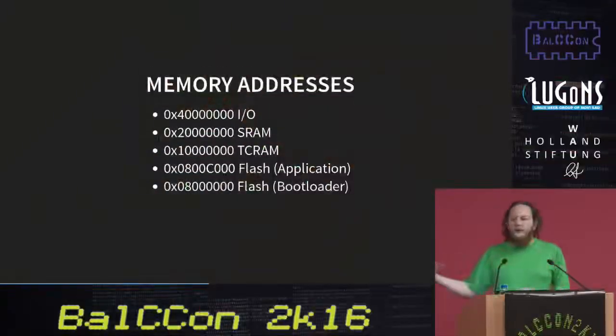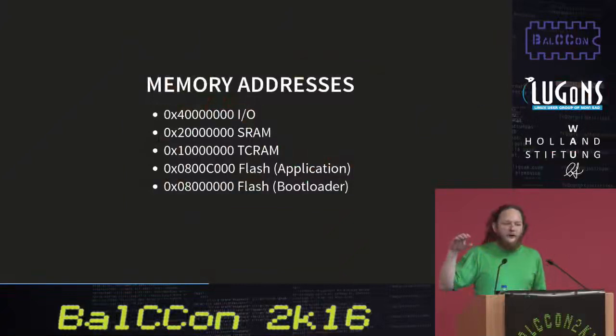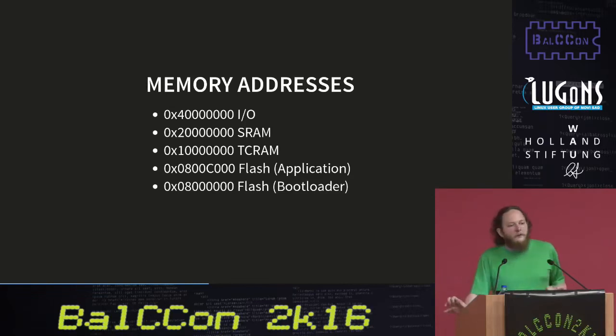The first thing you need to know is where things are in memory. Unlike Unix or Windows, where you have a varying memory layout per process with address-space layout randomization moving things around, on an embedded system, everything is stuck at a fixed physical address. And there is no such thing as virtual memory. So all of the I/O ports, when you read from a serial port, when you write to a serial port, when you access the USB controller, all of those addresses begin with a 4.